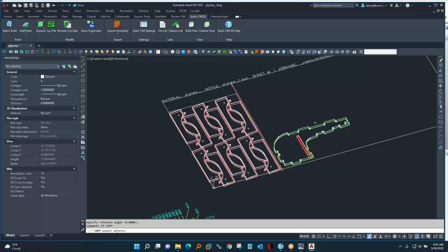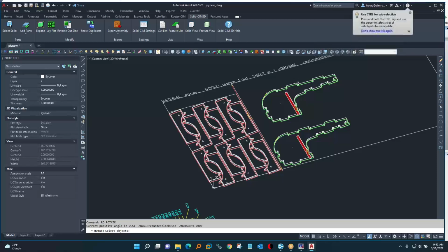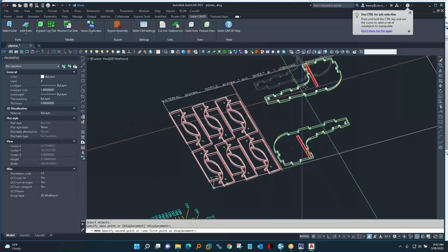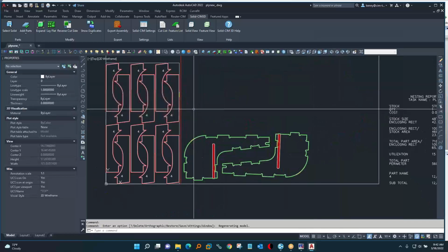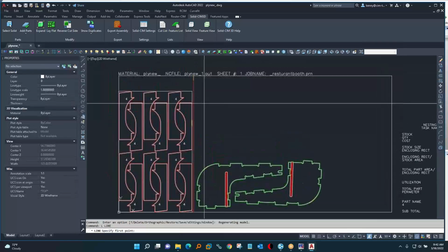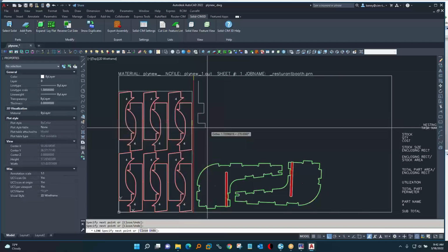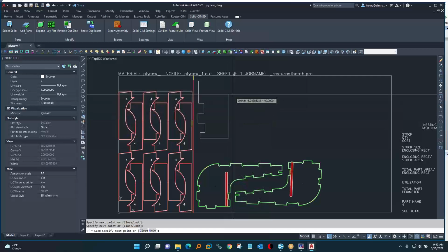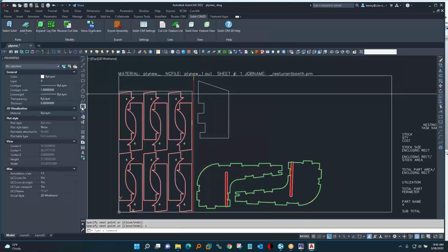And of course, because we're inside AutoCAD, we can use any of the AutoCAD commands right on parts and toolpaths. So if I want to rotate this one and then move it here, I'm laying out my own nest, for example. And of course, you could draw your own parts in. Nobody has a better drawing program than AutoCAD. So if you're going to draw in 2D, compare that to any other CAM program that has lines and arcs commands. Okay, AutoCAD does it a little better and easier.